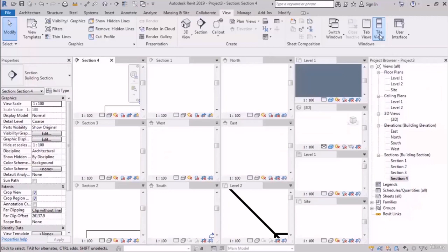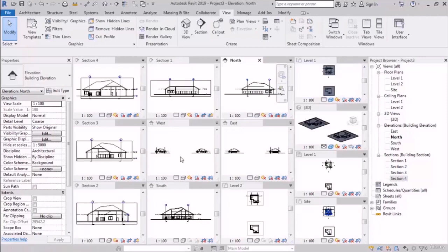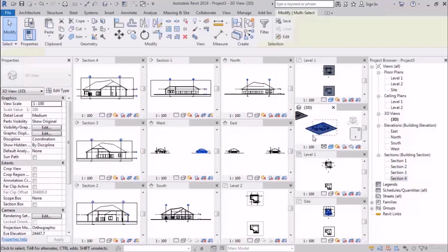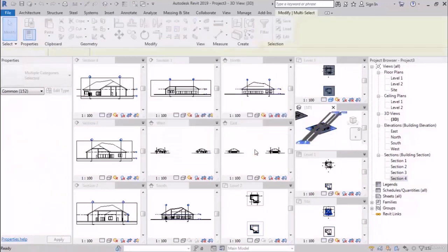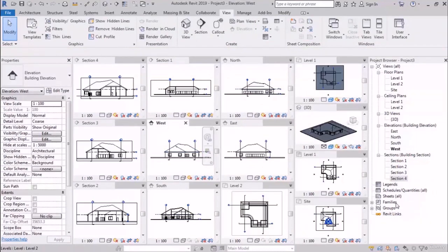But now we can't see our project between these. And we actually need something like the zoom extend that is in AutoCAD, that fits the project in view. In Revit, the shortcut of the zoom extend is called ZA. If you press ZA, you can see that's how it will be. For example, I will delete one of these. And again, I will press ZA. As you can see, our project will fit in our view.